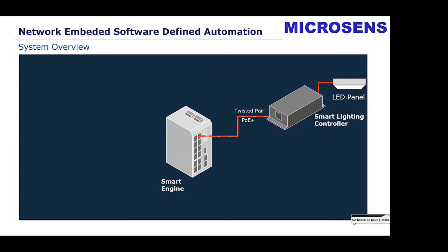Important is that in this case, you can use only LEDs without any integrated driver, so it's only the naked LED panel. In this concept, we have several smart light controllers from 1 channel up to 6 channel. I will come back to this concept later on. But the general statement is you run a device in the room over PoE, in this case, LED light.